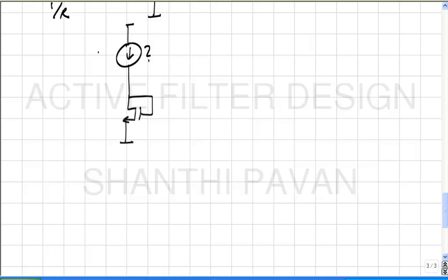Put a voltage across a 1 by R resistor and see the current flowing and compare it. So you say, okay, I am going to pump a current I into the device. This voltage will be some VGS, which is VT plus delta V. If 2I by delta V is equal to 1 by R, then I is the right current.